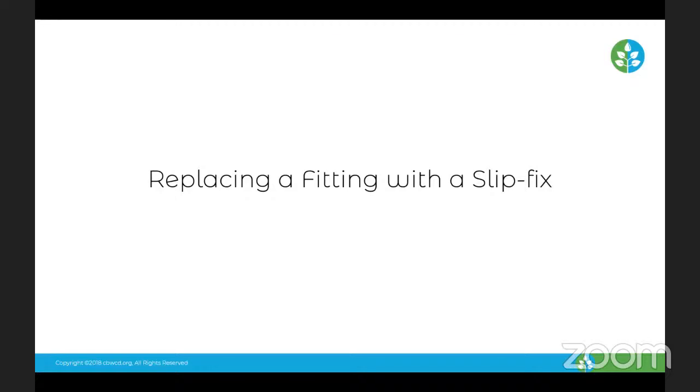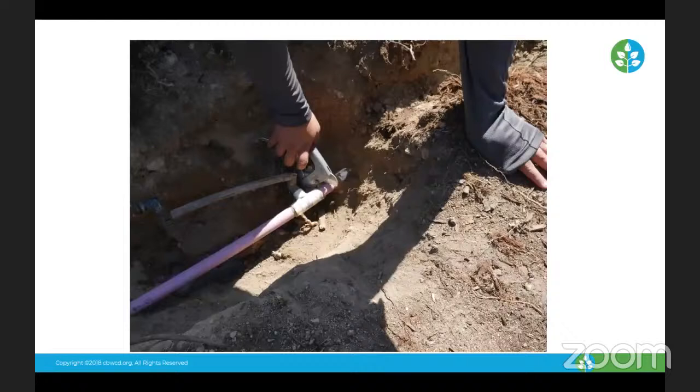But it is perfect for doing repairs after the irrigation valve. Like this area here, we had a broken T where we needed to cut out the T and replace it. As you can see, when we cut that out, we have a big gap in our PVC line now. A couple options we have. One option is getting a coupling, which is just a solid straight through socket. We would have to put one here, one back here, so multiple areas of gluing, and then glue in a new T.